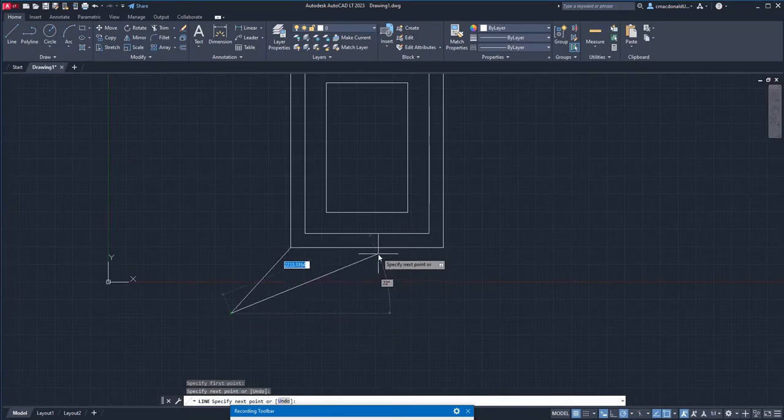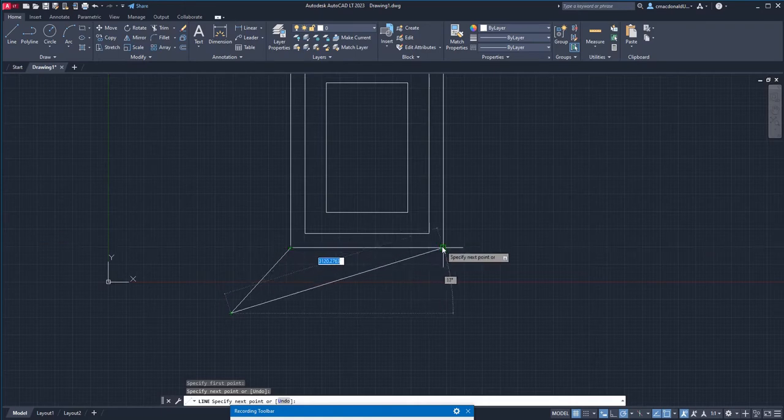Now watch this. When we try to bring it to the midpoint, it doesn't give us the option, but you see these green boxes here essentially light up when AutoCAD is trying to recognize where it wants us to put our snap to. So if we try picking here, look at that. It's putting the green box there because that's where it's going to take us in a second. So even though I can put it very, very close to wherever I think the midpoint is, essentially what it's going to do is try to instead snap me right to one of the endpoints.